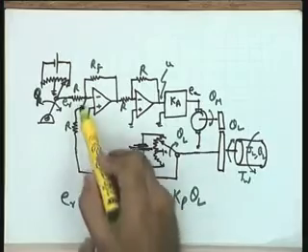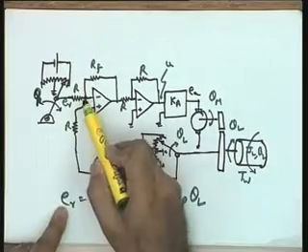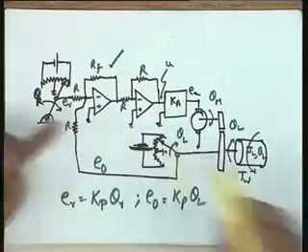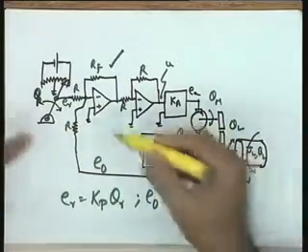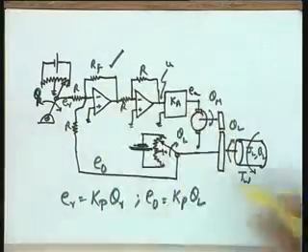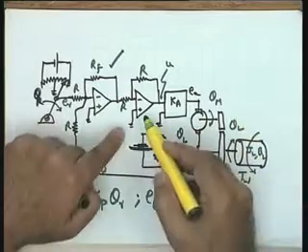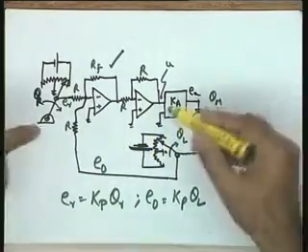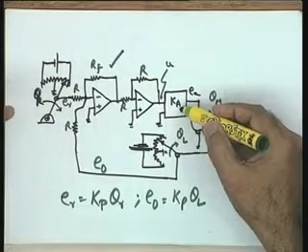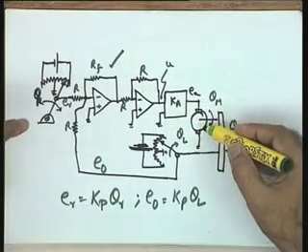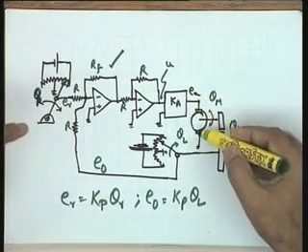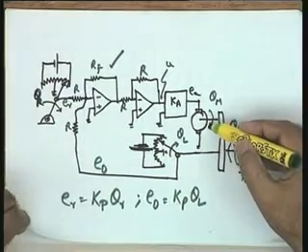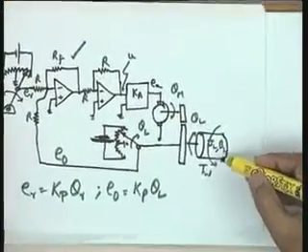Okay. Now this voltage ER minus E naught is being amplified. So it means this particular amplifier is an error detector which gives you a voltage proportional to the difference of the two. Here again I have an inverting amplifier, so that the minus sign is taken care of. I have a power amplifier over here, so that this particular signal is to drive the motor. This motor produces the torque, and this particular torque is required to drive the load.